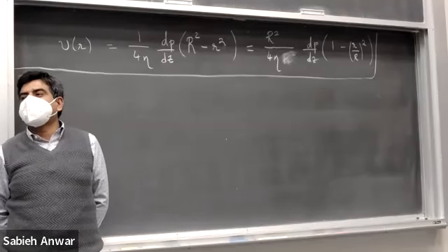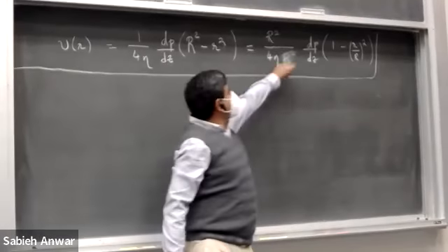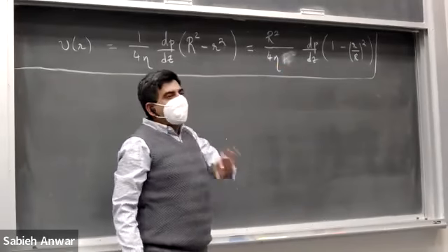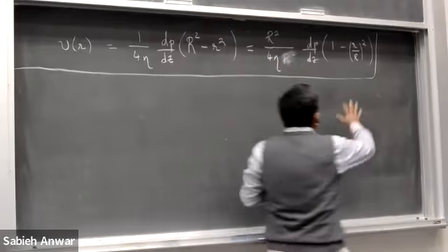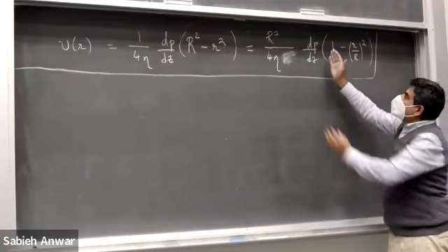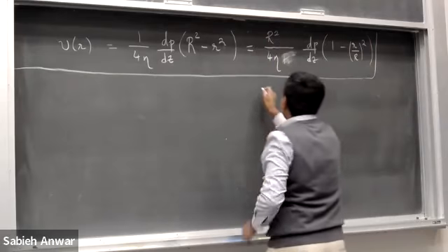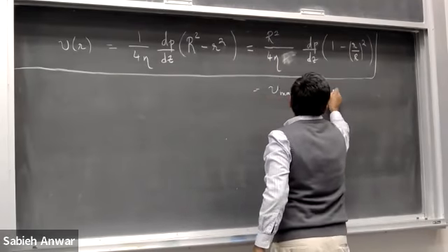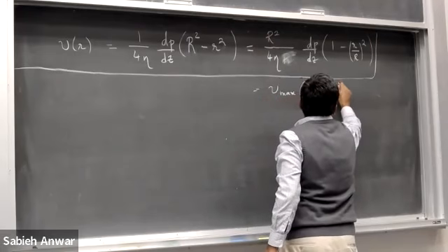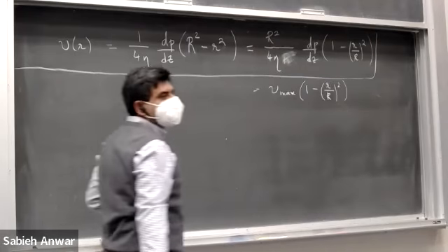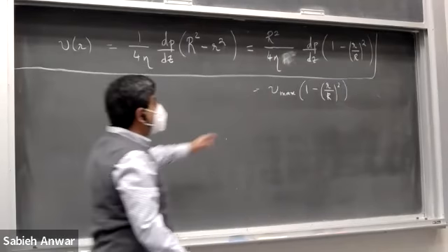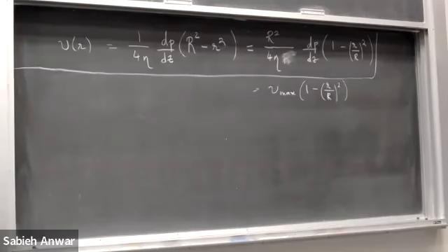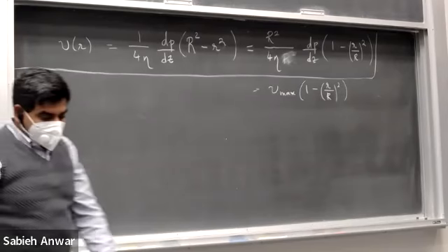All right. So all of this is a constant. By the way, the maximum speed is at small r equals 0 along the axis. So this term goes to 0, this term goes to 1. This is the maximum speed here. So I can write this as V max times 1 minus small r over capital R, squared. Now this dp over dz is a pressure gradient. Now we're getting to Ohm's law, slowly.